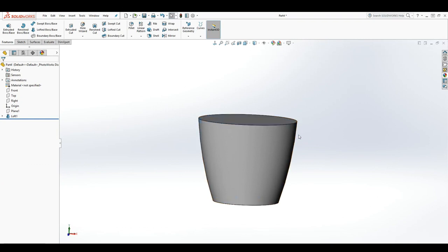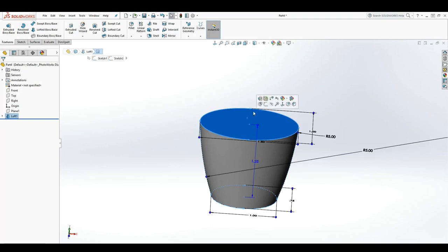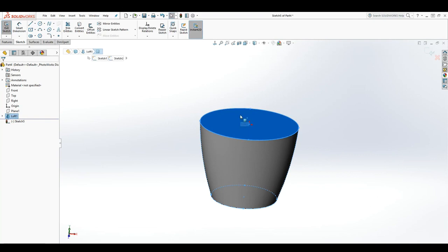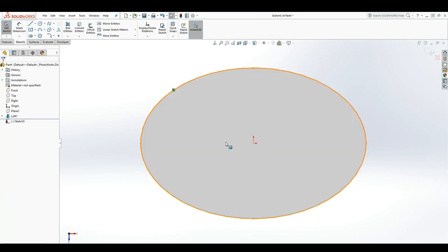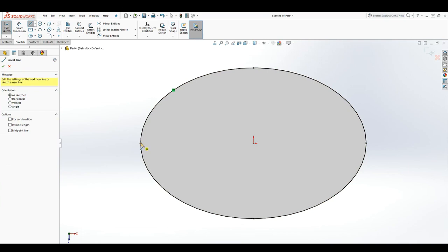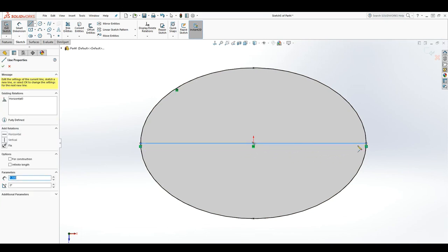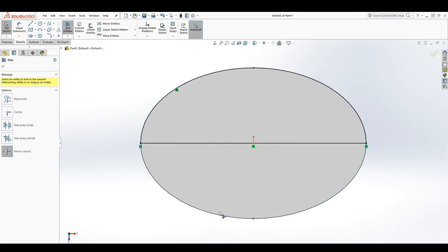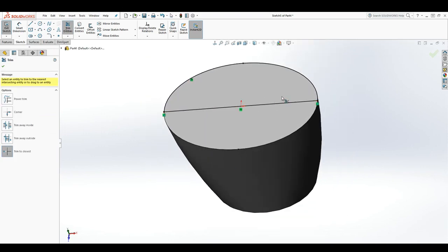Another way you can actually do the loft tool is, let's select this face and click sketch. And while that face is still selected, let's click the convert entity to make a sketch of that face. We'll go normal tool, and let's draw a line from this point to this point. And now let's trim half of that line off, so we have just half of that line.